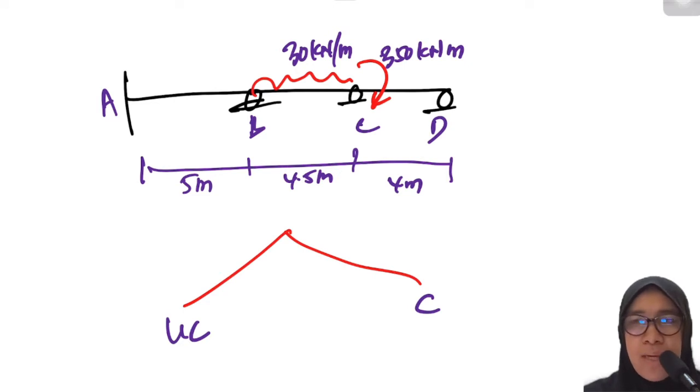We only need to consider the degrees of freedom in the Y and Z directions, because in a beam there is no axial force and no horizontal displacement. So we don't need to count the displacement and force in the X direction.